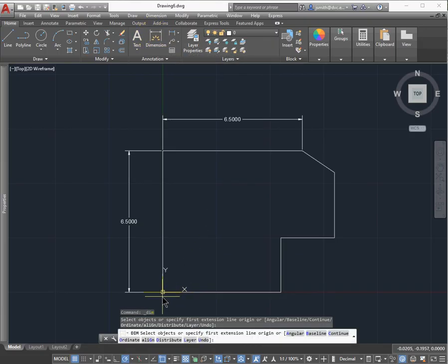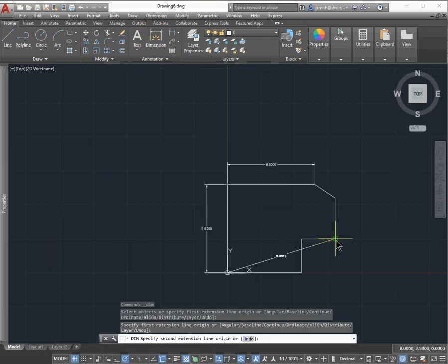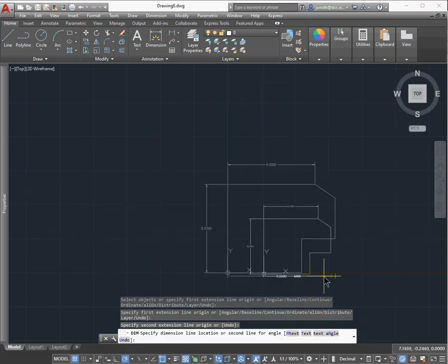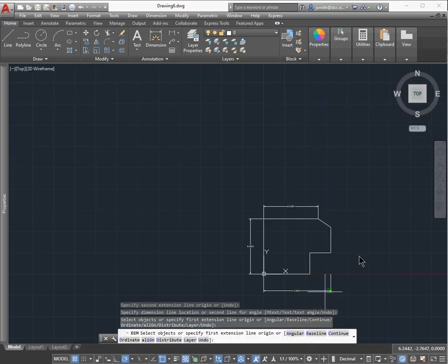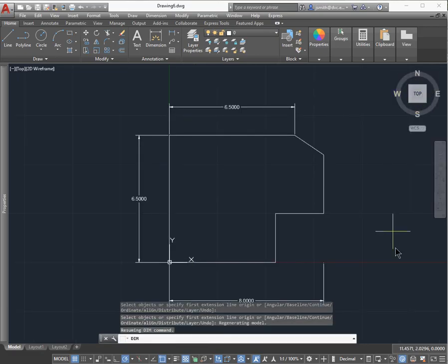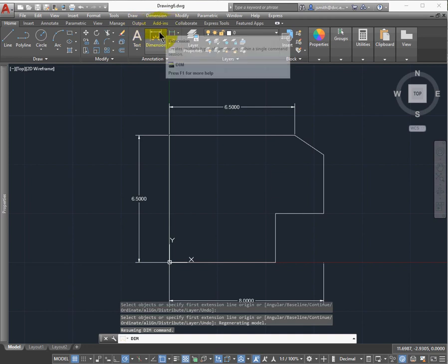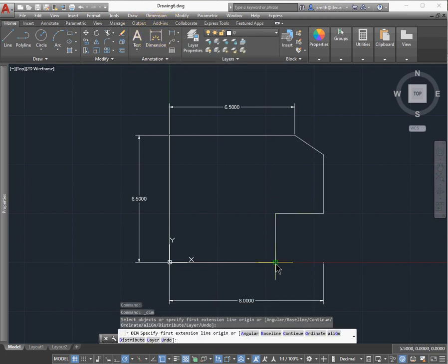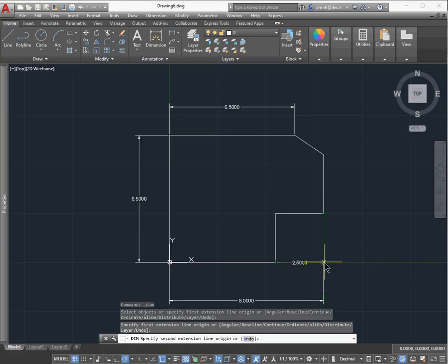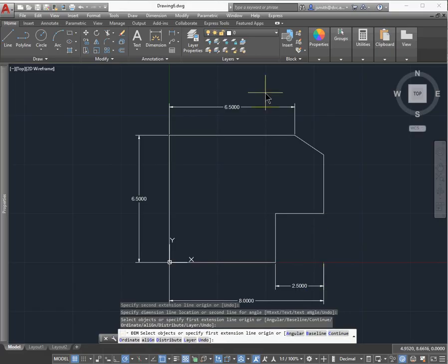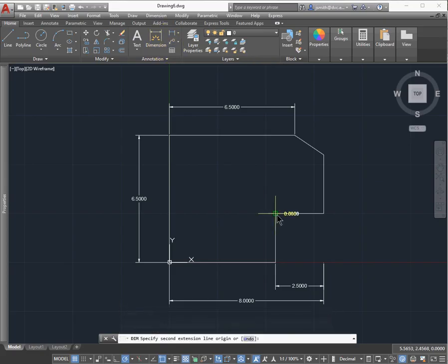All right, and so I can use this wheel at the top and click on top, and that'll center everything. So before I get too carried away, I'm going to go ahead and dimension everything here, and you essentially just snap it on the corners and then drag your mouse down or over, depending on where it needs to go. And I'm zooming in, scrolling in with my mouse, zooming in and out. So just verifying all my dimensions before I proceed. And so we've got the 2.5, that little square, and that 5 inches. So let's just verify all this. And again, I try to do this in the same manner that our textbook does it. This way, I don't have to dimension it at the end because it's already done.